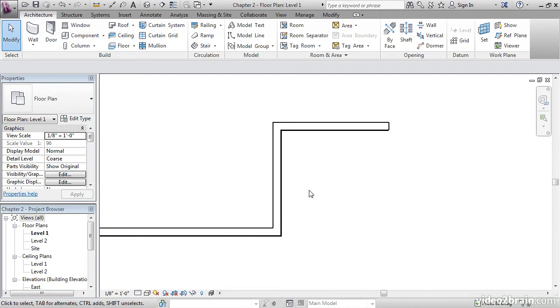This brings up another great point. The problem is, they don't look very well, do they? We selected this complex wall and we went through and looked at all these awesome properties, but we're seeing this in our plan. That's not acceptable. The thing is, we have what's called the View Control toolbar. This toolbar controls the view state of the objects in the view window.